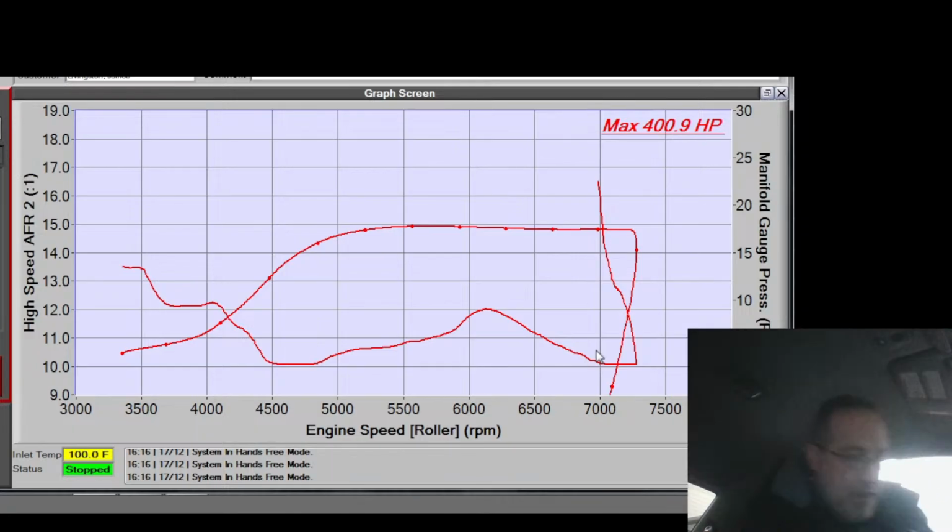So with heat range, the spark plug is in the chamber, and in the chamber we have post-combustion products, byproducts of combustion, often involving carbon, as well as small bits of oil that we burn off, additives that are put in the fuel and all that. And that stuff plates out. Carbon and all that stuff will start to stick to things inside the cylinder. You get carbon on a spark plug, and then you just short it to ground, and it no longer runs. So the spark plug has to be hot enough to clean itself. That's the key. The heat range is about cleaning it.